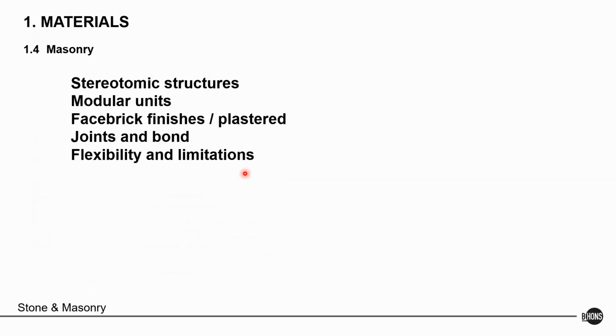Just remember, these often refer to stereotomic structures. These are structures that, if you think about monolithic structures, is another word you can use for that. So it's not often used for more than two-story buildings. If you go any higher, you actually have to start using it as a frame system. I know there are engineers that use masonry in five-story buildings and so forth, but it's in very specific ways they design it, and they specify the brick and the cement that you use as jointing.